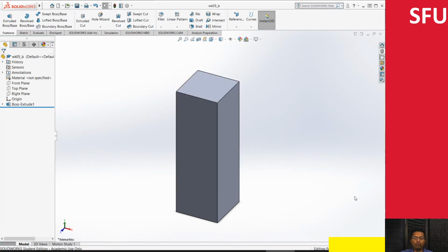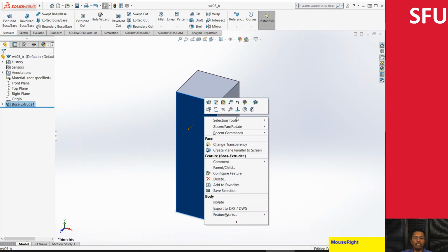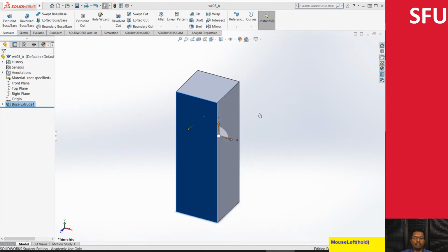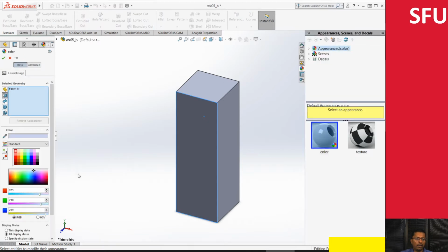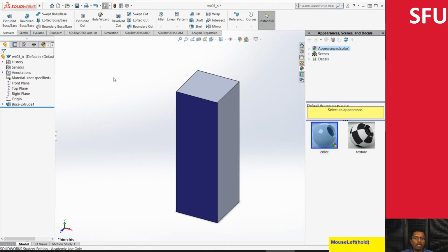So right now I have two parts, and just to illustrate what's happening, I'm going to select this face and then change the color setting. Click on appearance, and then click on the face, and let's pick two colors. I'm going to do maybe blue and orange. So blue for part A, and save this.